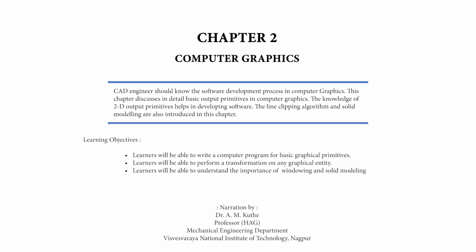Limitations. Number 1, the surface model has no knowledge of volume, so it cannot easily be used to calculate mass properties or to create sections. Number 2, surface models, like wireframe models, are incapable of handling spatial addressability, that is, they are incapable of verifying whether two objects occupy the same space or not. Number 3, surface models are slow to render and computationally intensive. Number 4, surface modelers store only the geometrical information of the object, like the wireframe modeler.